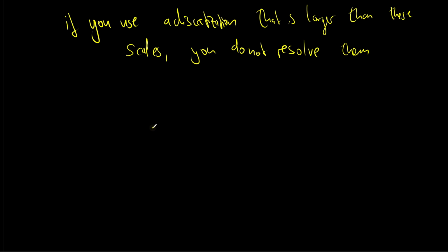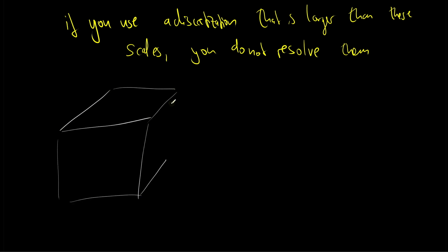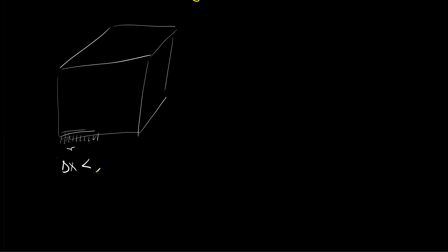So for instance, if you look at 3 dimensions, because turbulence is a 3-dimensional phenomenon, and your computational domain is, let's say, this box here, and you discretize this box in this particular way, then this distance delta x between 2 discretization points, which make up these small cubes, has to be smaller than eta, and eta was of the order of the Reynolds number to the minus 3/4.